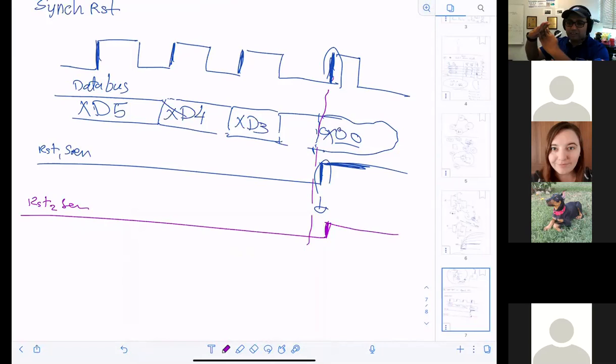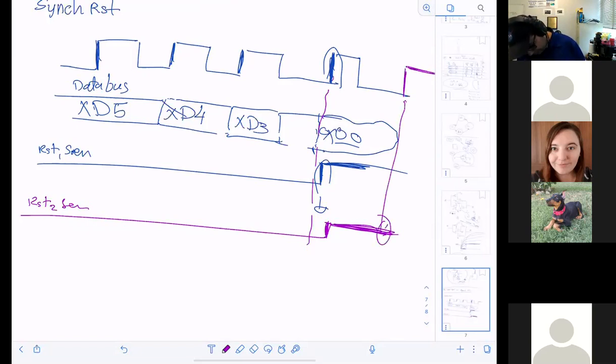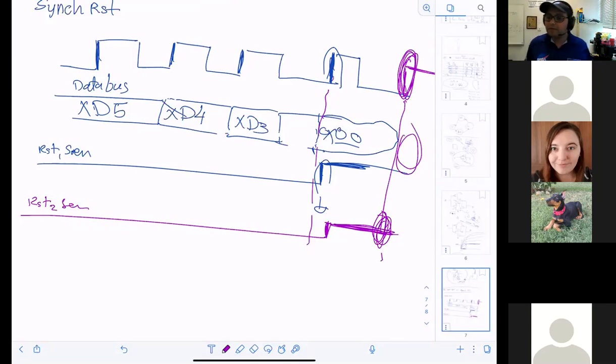Both of them have to catch each other at the same time. So that means when it will be reset, next cycle, that guy will be high forever. Oh, so if it doesn't hold that reset information in the buffer. Yes, look here, this is high and this is high already. So that guy will reset here. The time the reset is high and meets the positive edge, data will be reset. That's called synchronized. Now for the asynchronous.